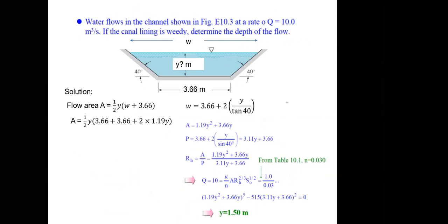If you want to have, like, 10 cubic meters per second of flow rate, for example, to run a turbine, to get that Q, how much depth do you need for the channel? This is another question that arises that can be solved using the Chezy-Manning equations. Let's say we have the same shape but different geometry, a different height in our case. We don't know what the height is. We want to determine what the height is, so we can have the discharge, for example.